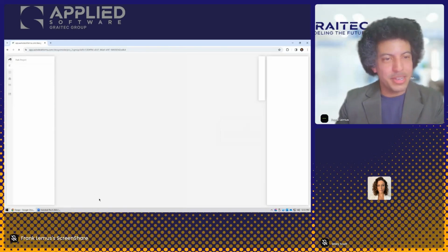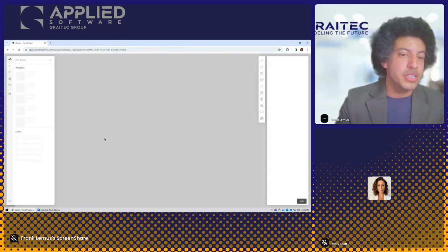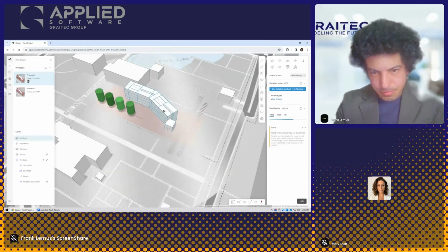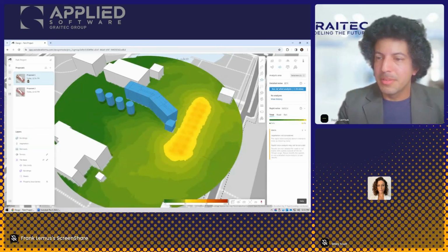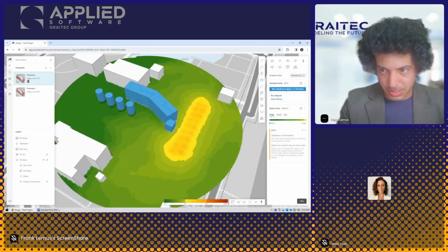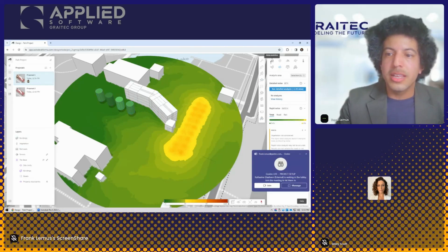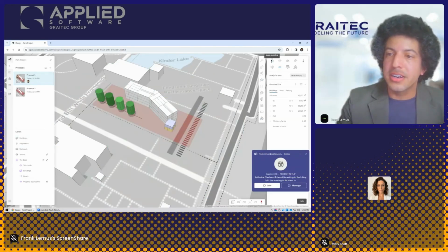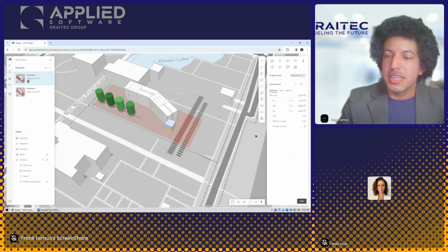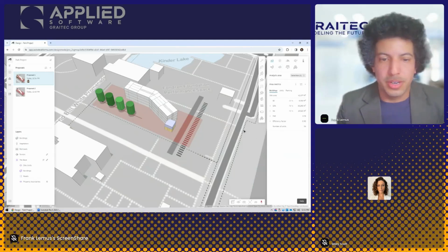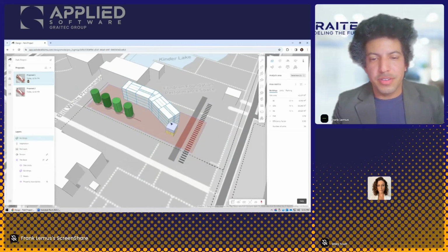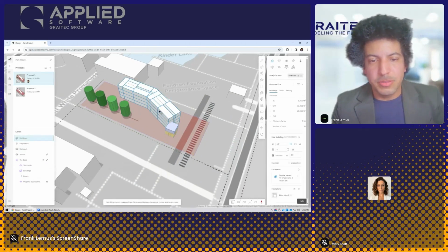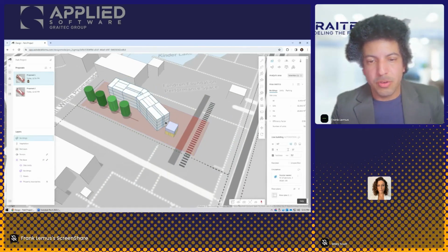I want to skip that because I really want to show you that you can put this in Revit now. It's causing me to reanalyze this stuff every time. Sometimes you can run detailed analysis, so I like to tell everybody, click here under area metrics. That's going to be the easiest or the lightest one. If you're on that, that's kind of like the default. Okay, now we've got all of this stuff here. Maybe I should move this building and not let it cross into the other one.